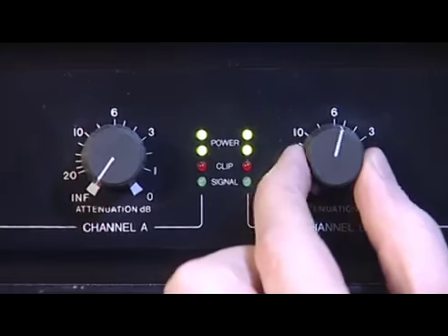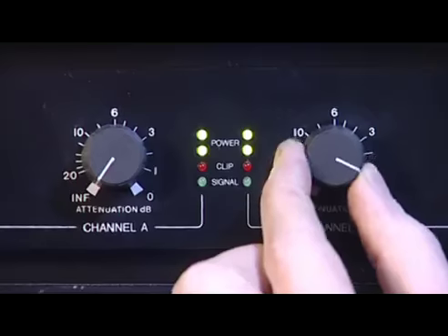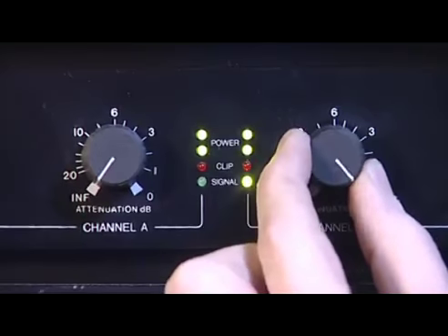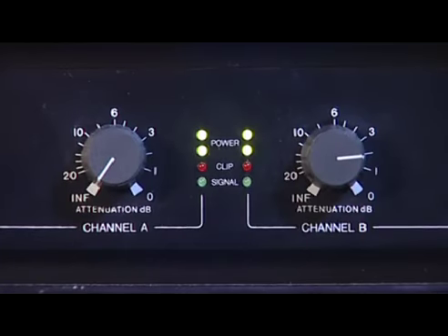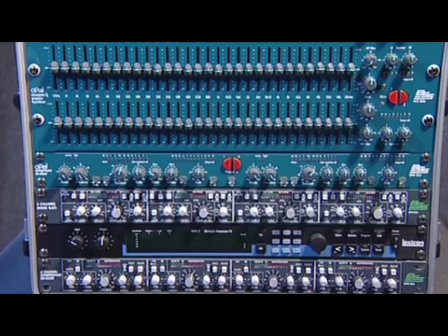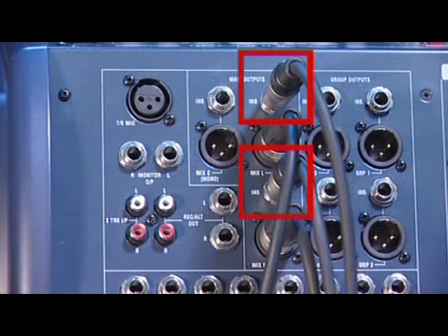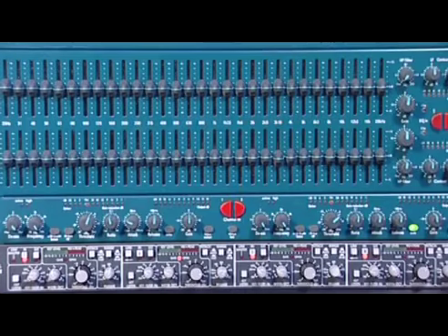Ringing out the system before the sound check is a good way to reduce the danger of feedback. You need to remember that during the process of ringing out, you can cause severe feedback which can damage loudspeakers, so be very cautious when turning up levels. Here's how it's done. Put a graphic equalizer into the mixer's mix insert points. Set all the graphic equalizer's controls to 0, which means that they'll be in the straight line centered on 0.